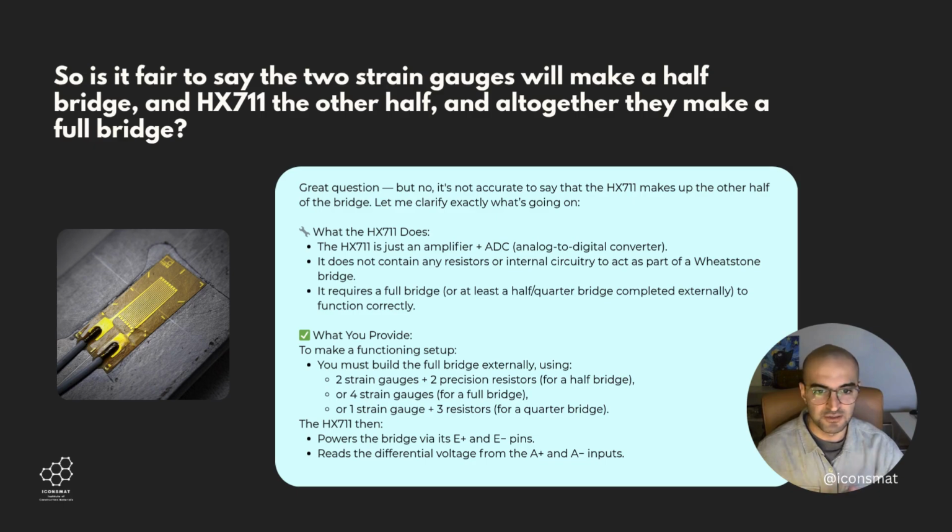And then the HX711 powers the bridge via its E plus and E minus pins, and reads the differential voltage from the A plus and A minus inputs.